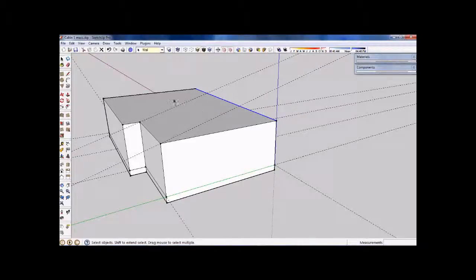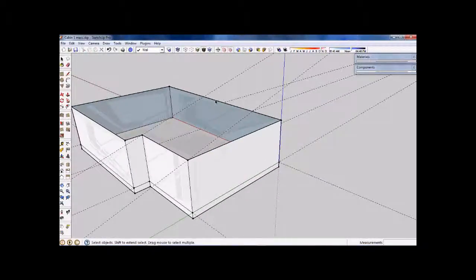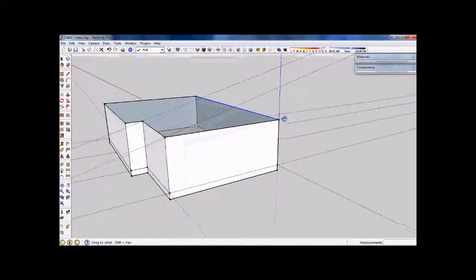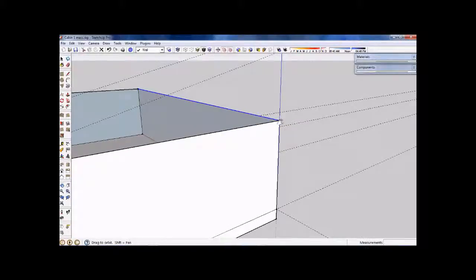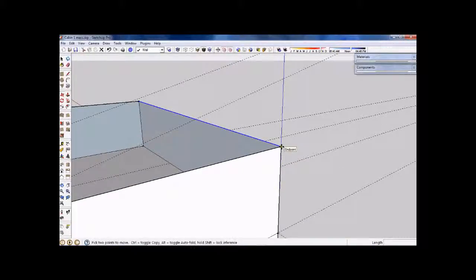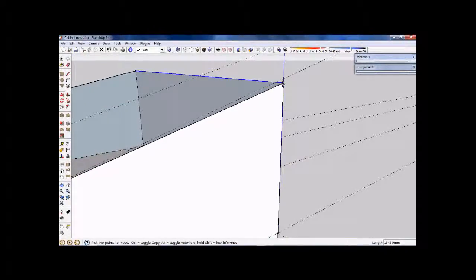So we need to just temporarily delete that ceiling. It's going to be easy to put back on in a second, so I'll just delete that ceiling temporarily. And while that's being deleted, I can now select this edge here. I can then go and find the move command over here, press the move command, and I'm going to move that edge from this end point. So I'll just click that point there and then drag it up until it finds there should be an on line, just to make sure that definitely is doing it.